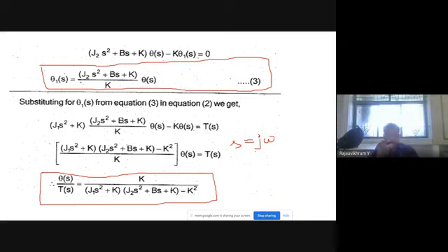So in the transfer function, you see that K is a constant, B is a constant, and J is also a constant. If you change these constant values, you can get one conclusion: for this value of the constant, we can get better efficiency, better performance, or a better result for the system. Based on this expression, you can change the constants. You get a conclusion as a control engineer: if this is the value we set as a constant, this is the output performance of the system. This way you design the system, and this is called control system design. Theta is the output, T is the input. By changing the output by input, you can conclude for which value of the constant we can improve the efficiency or performance of the system.